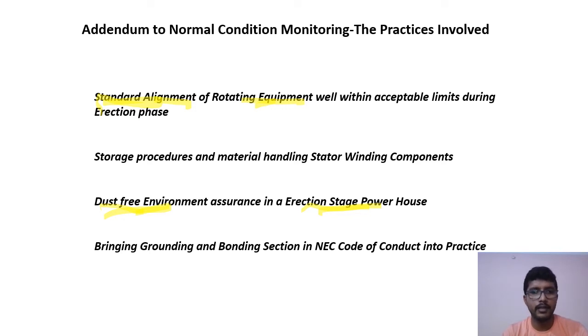But some arrangement should be made so that dust does not come in contact with surfaces which are being cleaned, machine surfaces or mechanical. At best, whichever surfaces need to be covered, we should cover them, and whenever required, we remove the cover and work on it. This is a very simple point, but very effective if practiced.